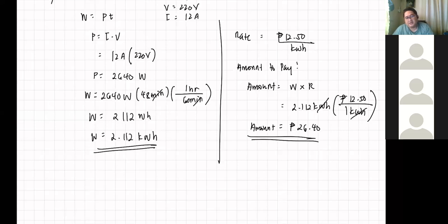Okay? So, using this principle, we can already at least calculate for our appliances, no? For example, our actual electric bill for the month. So how is that? For example, we know the meter of our electricity. For every month, you can record the number you see there. Record it for this day, then before the billing period, record it again, or when the Meralco people come to read it, record it again. Then if you subtract the latest minus the first recorded, the number you get is in terms of kilowatt hours. Then multiply it by a certain number, the average rate. I think the average now is around 11 to 12 pesos, no? So by using the kilowatt hours you got times the average rate, you can estimate your electricity bill when your billing statement arrives.